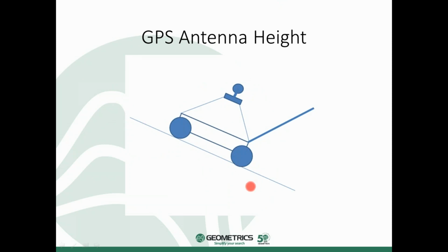So recently this version of the software also improved the IMU calculation, especially at high angles. So previously we would misreport some angles from the IMU, and for those who aren't familiar, IMU is the inertial measurement unit, and that corrects for the attitude of the cart, so the yaw, pitch, and roll.